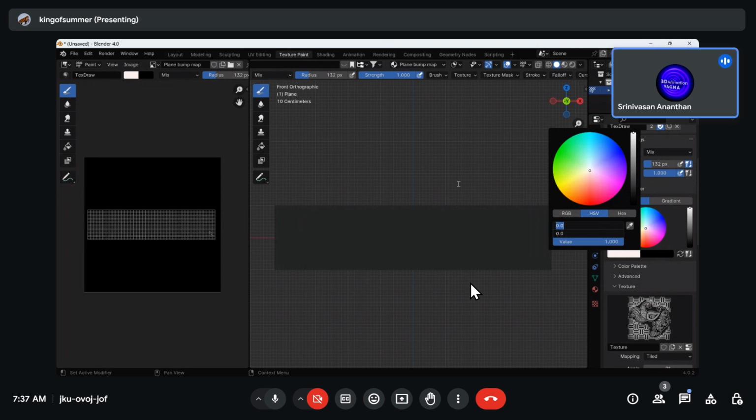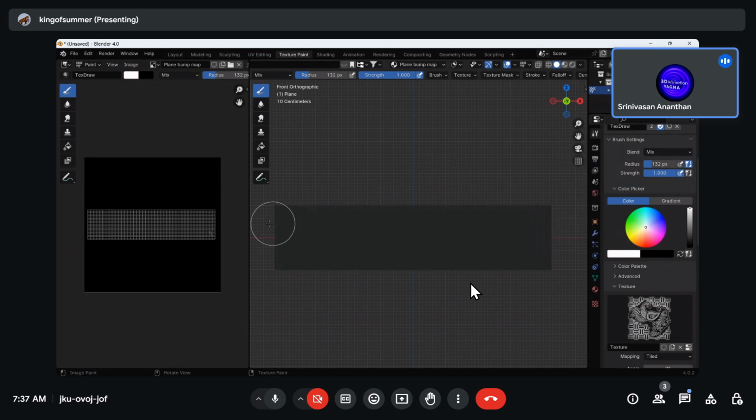Only then will the texture be imprinted on that plane without any intervention of colors. Otherwise it will come with color, and the original texture won't come there. So we should make it white in the bump layer while painting the bump map. Right. Now we have to change the texture. Go to active tools on the right side, scroll down. Mapping method should be stencil.